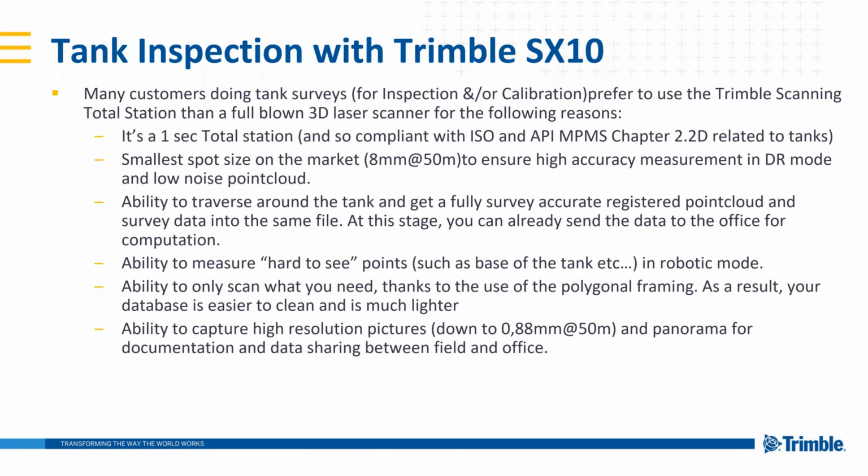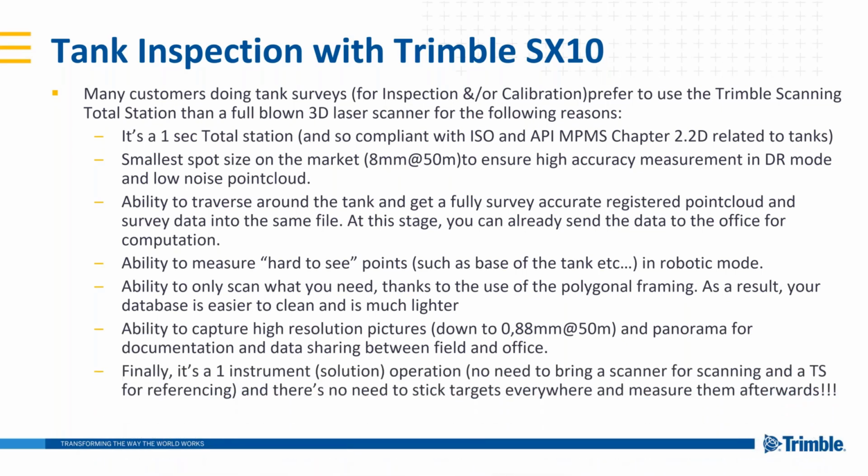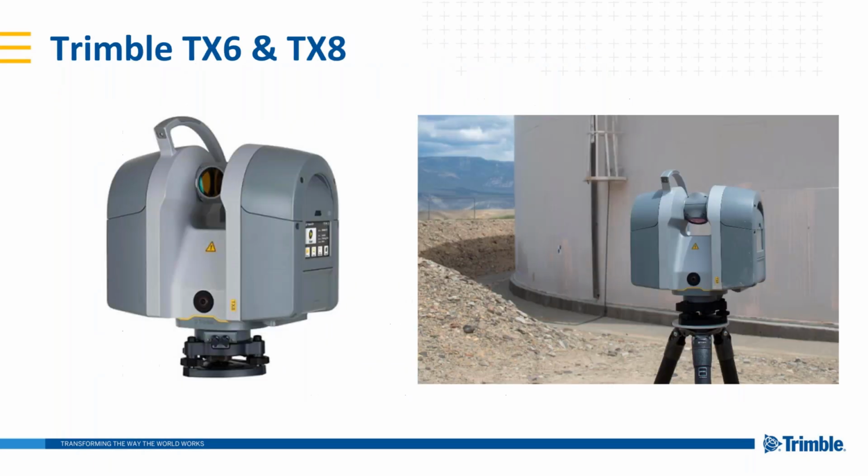And the cameras inside the SX10 are great and provide very high resolution images with a great zoom as well. And then finally, it's two instruments in one. So you get the total station and the scanner. So it's great, especially if you're doing storage tank construction. The example I gave you earlier, maybe you do find an area that is out of tolerance or not meeting the specs. You can use the very same instrument that you use to capture the data to then go and stake out and locate where these areas are.